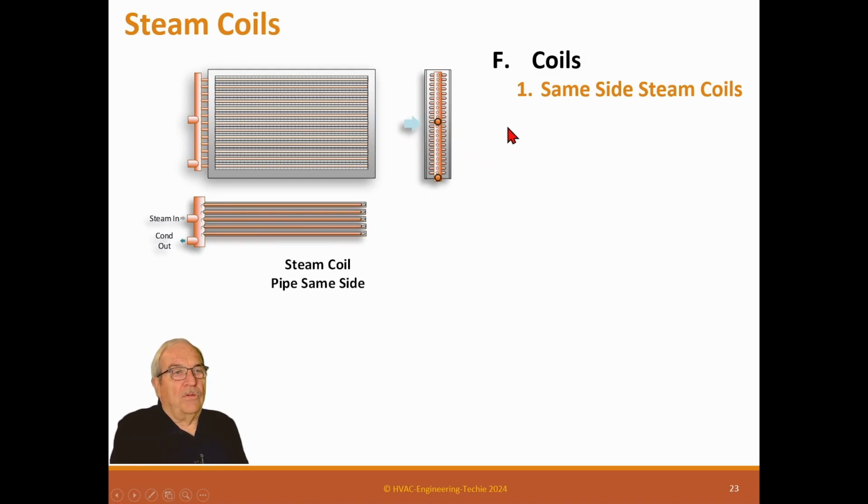And of course the air flows through the coil to change the heat transfer from the air to the condensate. These have, of course, aluminum fins normally on them, could be copper fins, to actually increase the area for heat transfer. 1 to 6 row, 8 to 18 fins per inch. You can get closer fin, but don't.